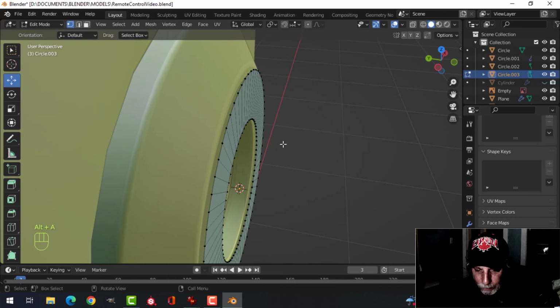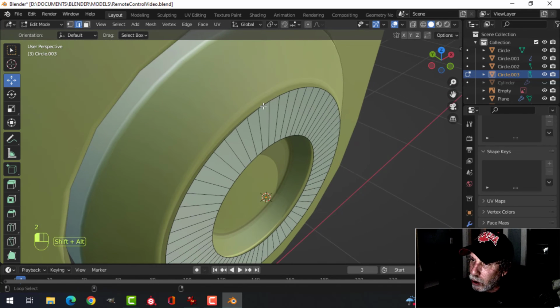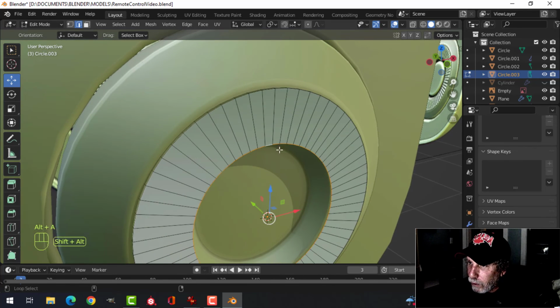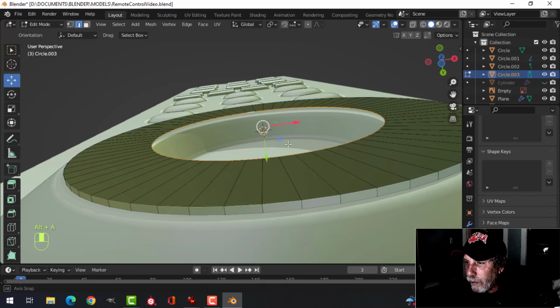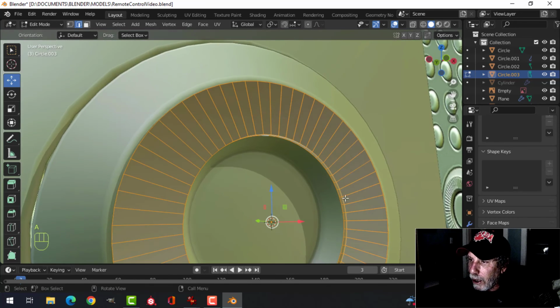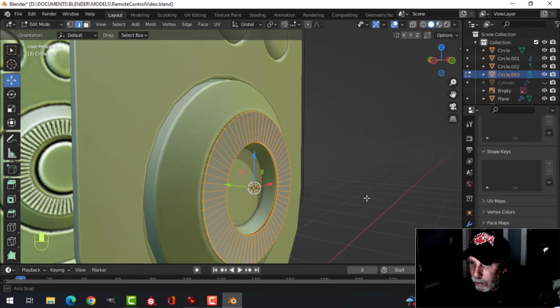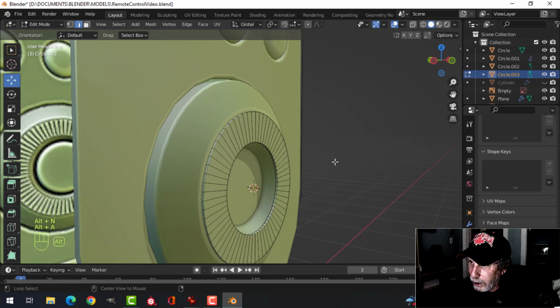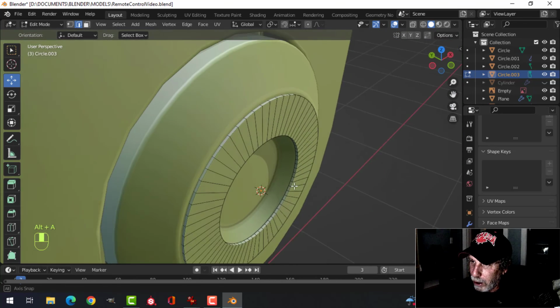So I'd have that, and then press 2 for edge selection, Shift Alt to click that edge, and extrude it back. Shift Alt to click that edge. E to extrude and just pull it back. Take the whole thing, and you can see it's sort of dark, sickly looking, if that makes any sense. So recalculate outside. Now look, you look so much better now.